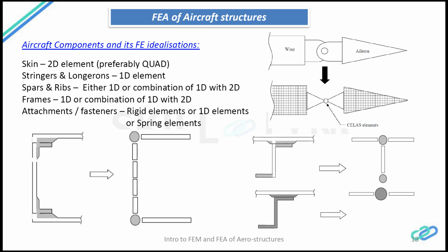In order to mesh, you need the geometry, and whenever the geometry is supplied, you have to decide whether the elements should be meshed on the outer mold line, or on the inner mold line, or in the mid plane of the geometry.